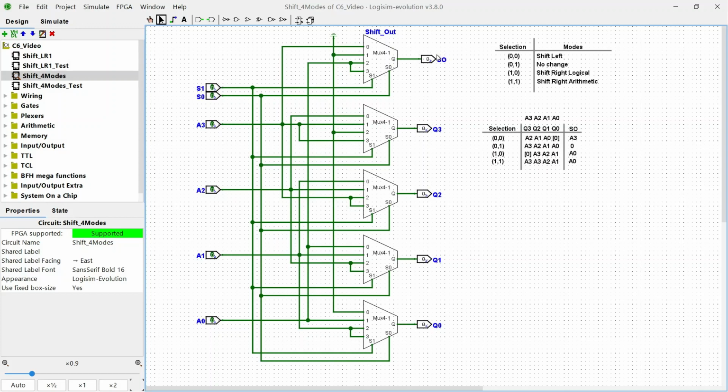And also the shifted out output. With the shifted out output, if we don't do anything, then the output is 0, because I don't know what else it could be. So it also has 4 options, and we can also use a 4-to-1 multiplexer to get the shifted out output. And that's it. That is how I designed the shifter circuit.